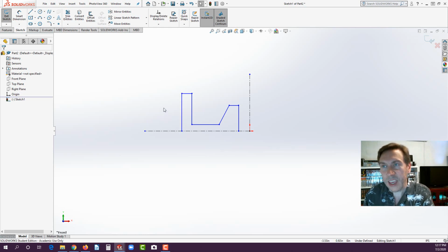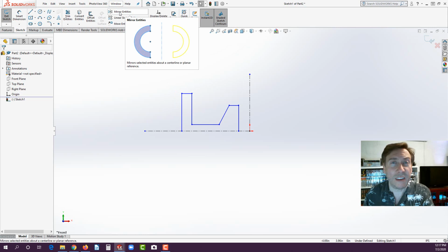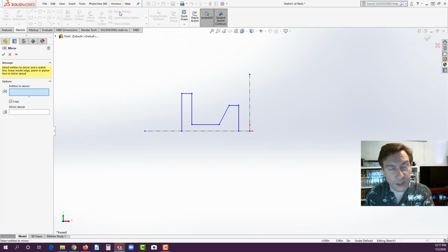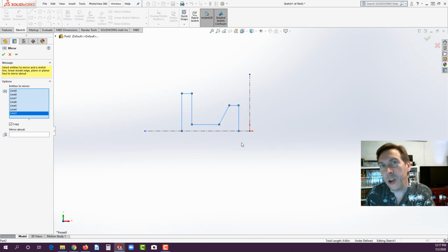What you can do is you can click on Mirror Entities, and last week we actually saw a couple different ways you could do this. We're going one route. This is maybe the slower route, but it's okay. It's so you can grasp the idea. Now select the blue lines. Now, could you group select like with the window? Absolutely. You could click up here and drag across, but don't include any of the center lines with it. Meaning if you go from left to right, make sure that those center lines are peeking out of your envelope that you're making. Kind of like this, I'll show you.